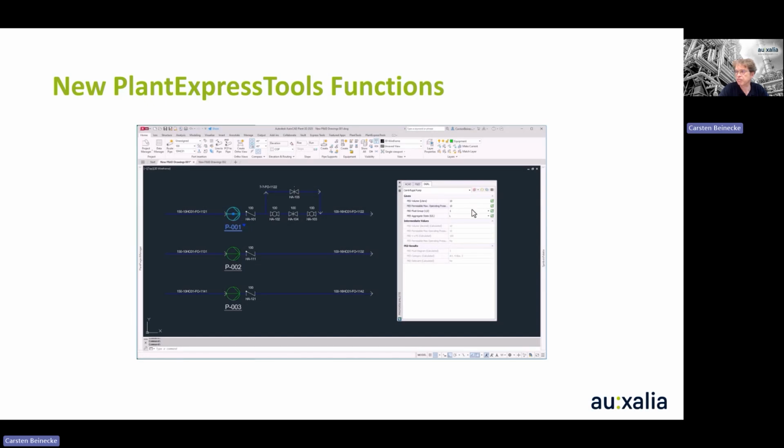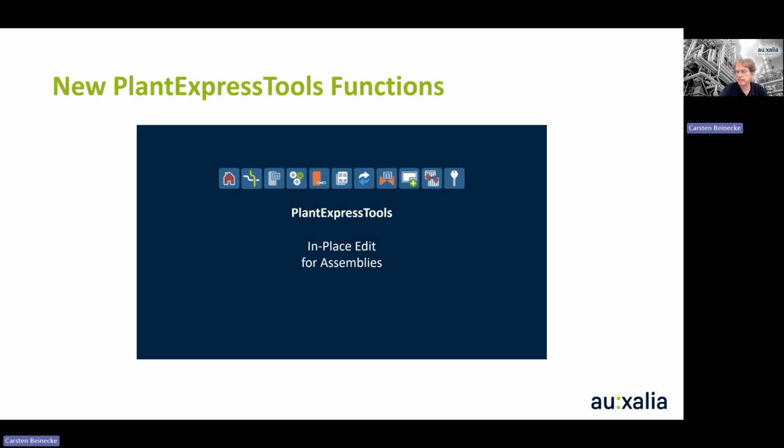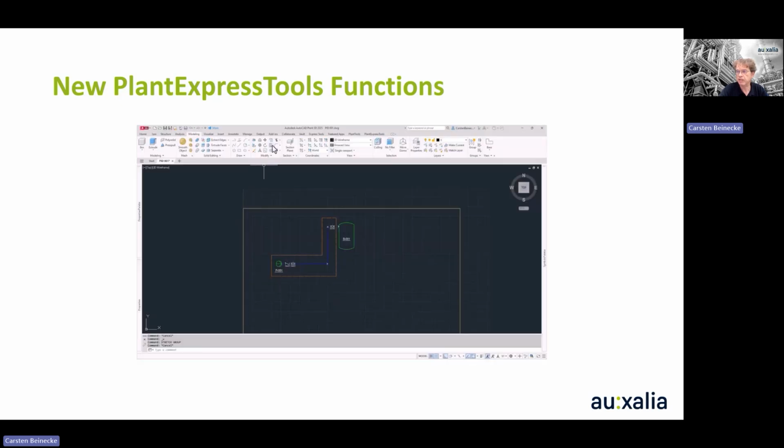Then you click and you're now in paste mode. First you select the objects or symbols which should get the data. It's not copied yet, you just select. Now you click on the button again, and it pastes into the symbols, and you can see they all have the same values. You can also switch to a drawing while you are in that mode and click again, and then it copies it there. Then you deactivate the feature, and you see here, for example, in the heat exchanger, the 4 values.